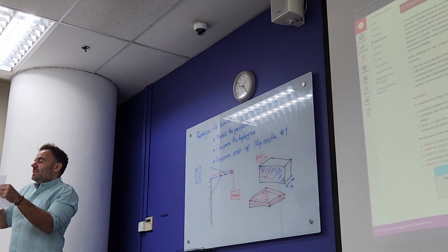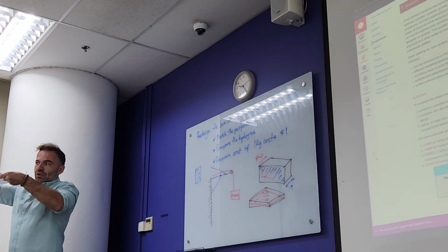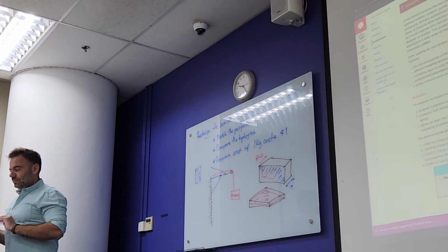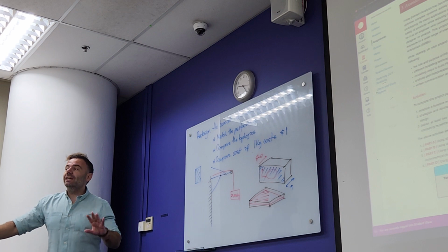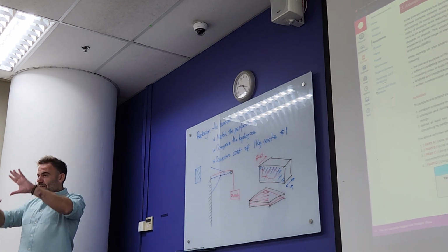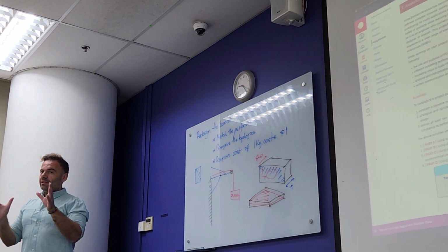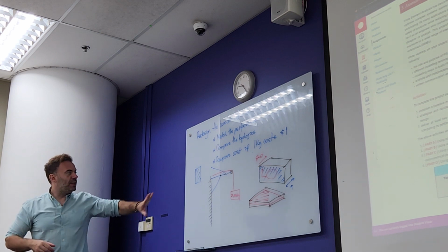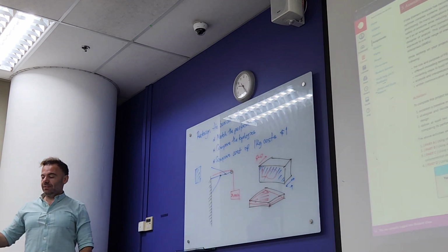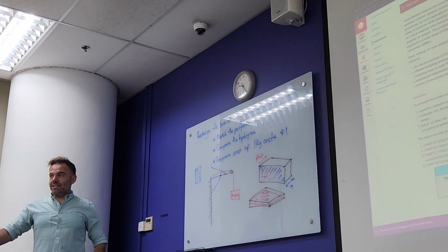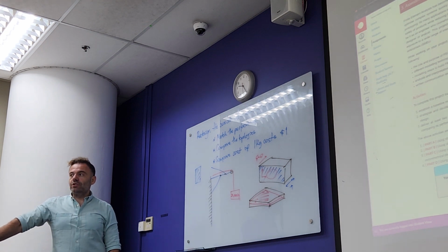But you will see it needs to be loaded like this. Yeah? So that's the difference. A shell is a 3D object, lives in 3D space. A 2D solid lives in two-dimensional space. Does that make sense? So there's no 2D shell. That doesn't exist.